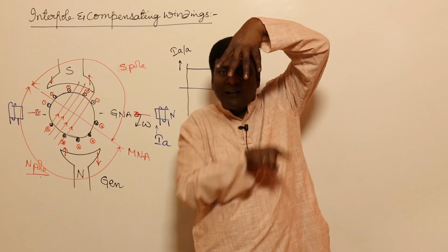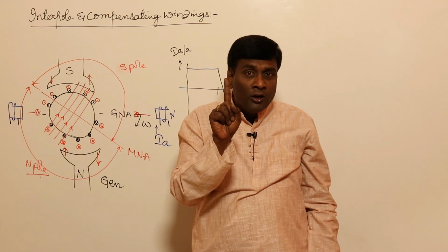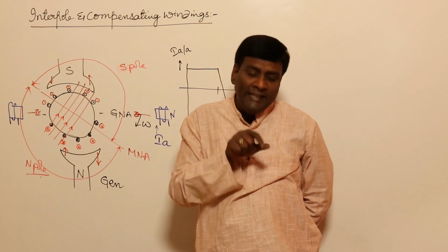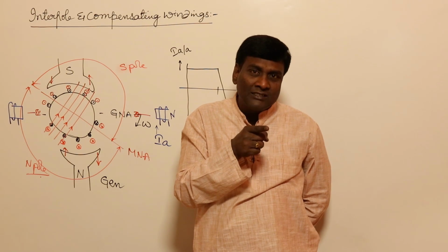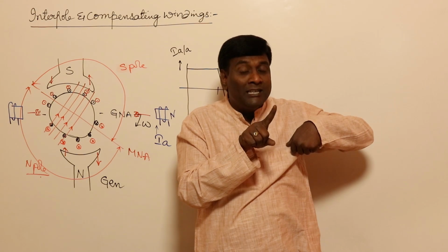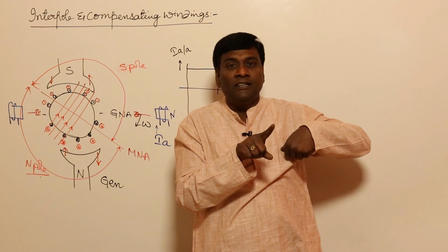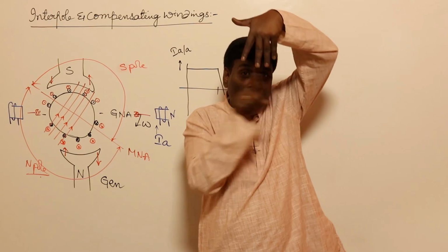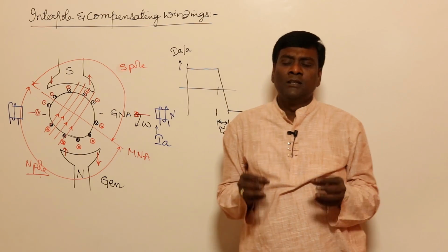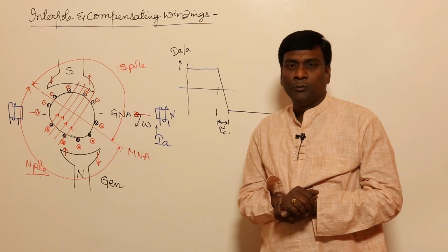Because for example, this is the flux. If the conductor is getting rotated, because of this flux, an induced voltage will be there. Now normally, in a conductor, when current reversals happen, induced voltage will be there. Now if this particular conductor's induced voltage, because of current reversals and inductive reactance, can be compensated by flux, current reversals will become smooth and commutation will become smooth. That is my point, right?